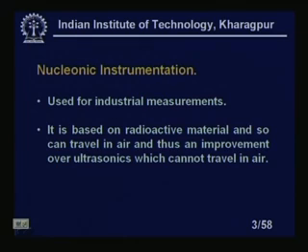But this is a disadvantage also, because in many situations we may need to transmit the signals. All these methods, that means ultrasonic methods or nucleonic instrumentation, are non-invasive techniques. So, in some cases, if I want to launch these rays through the air, it is impossible in the case of ultrasonics, but it is possible through nucleonic instrumentation or radioactive sources.